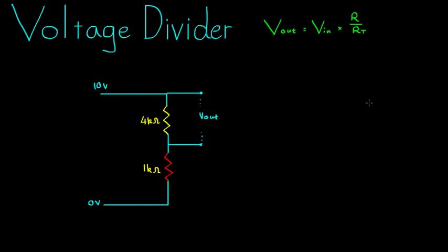The voltage divider equation. Efficient, intuitive, easily applied, and quick to learn. Welcome to the lesson in which we look at how to solve for the voltage across specific components without resorting to any kind of current formula.